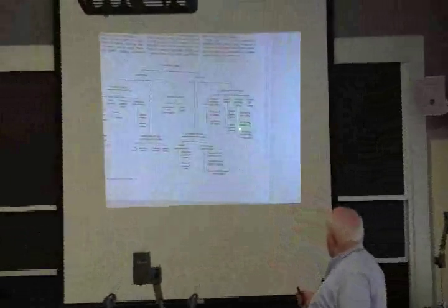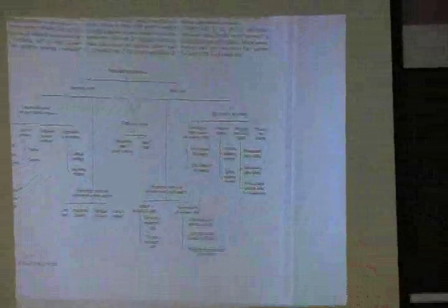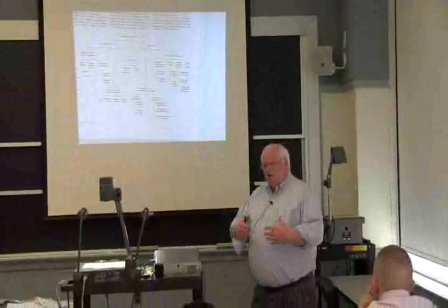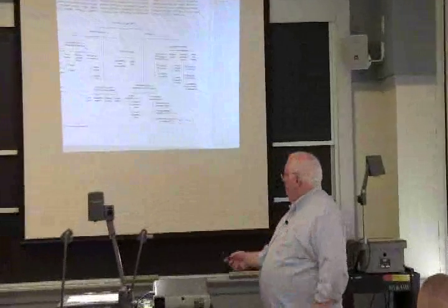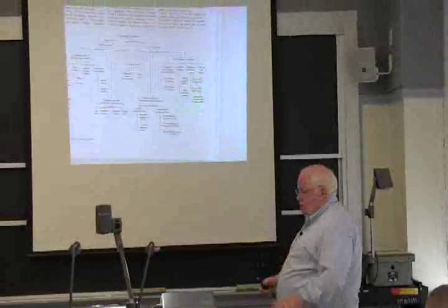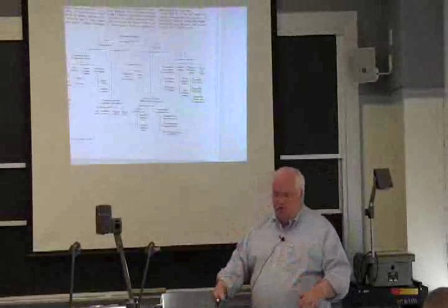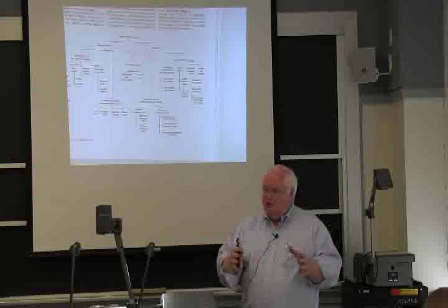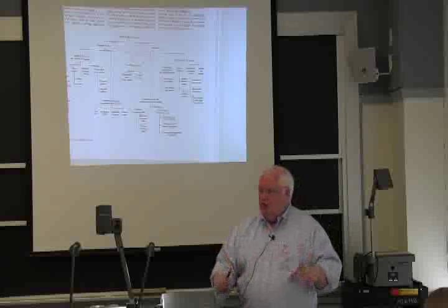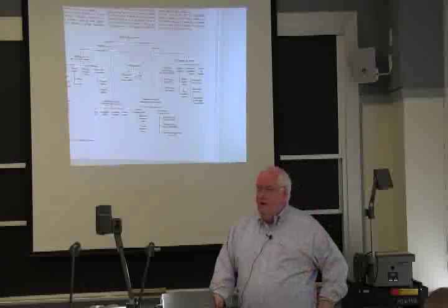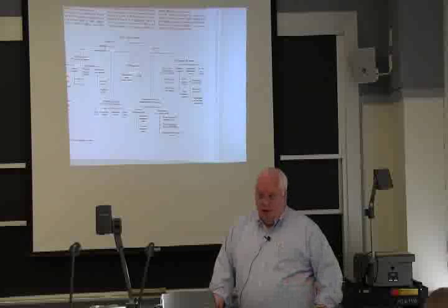It's a slurry thixo casting where you essentially freeze it hard, but you've created a structure that it turns out when you heat it back up, you can end up with a rheocast type of structure. And thixo molding, where you actually end up with something that's soft, and if you use dies at the same temperature, you can actually mold and get a shape to this stuff, kind of like playing with Play-Doh. That was all developed here at MIT.